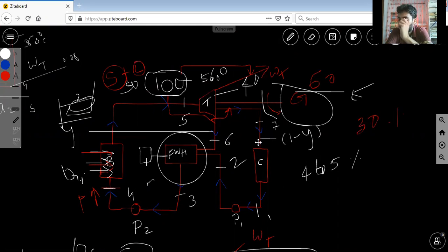At constant pressure, the temperature is increased from saturation to the superheated condition. Heat supplied is continuously increased, and if you increase the boiler pressure, the temperature is also slightly increased. You can find that data in the previous lecture.